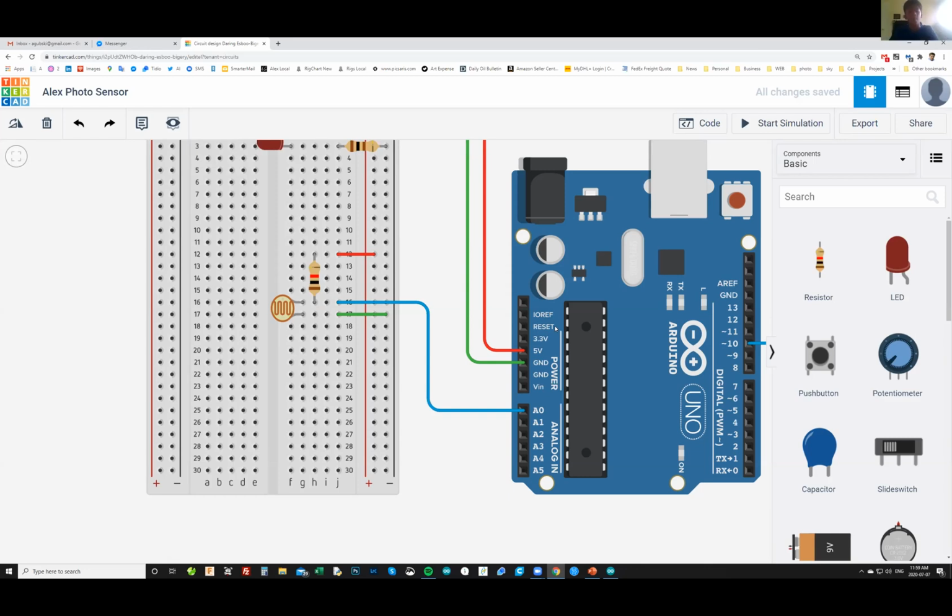The photoresistor looks like this little thingy. There are two of them in the little bag, this little plastic bag. So are we supposed to build it? Yes. Use that schematic that I just showed. You can unplug your potentiometer, and instead of the potentiometer, you use a combination of a 1K resistor and one photoresistor together. You don't even have to rearrange the wires much.